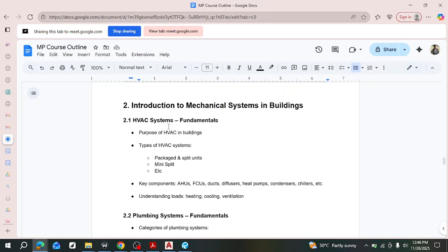There are some chapters in ASHRAE, for example, that give you an understanding of the amount of air to introduce into a space based on the use of that space, so based on the number of people in that space and then based on the use. For example, a commercial kitchen obviously needs more air than maybe an office that has just one person. So it also enables you, in your equipment selection and calculations, to size properly so that you don't undersize or oversize.